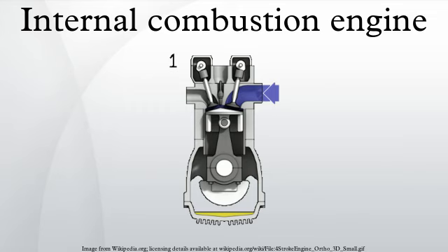Obsolete. The very first internal combustion engines did not compress the mixture. The first part of the piston downstroke drew in a fuel-air mixture, then the inlet valve closed and, in the remainder of the downstroke, the fuel-air mixture fired. The exhaust valve opened for the piston upstroke. These attempts at imitating the principle of a steam engine were very inefficient.